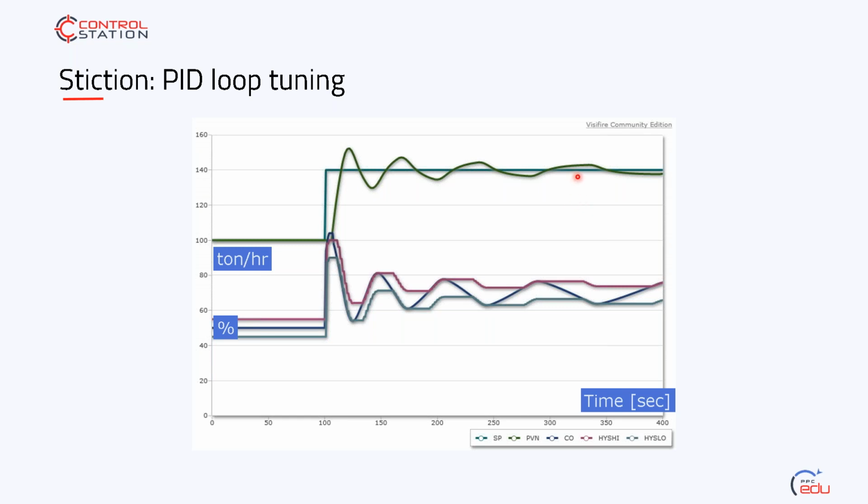You can set your own limits on that based on how close we get to an alarm with the loss of 1% of instrument range, and that should drive your decisions: are we going to do something about it now? Next week? Or on our next shutdown? You can track that through your predictive analytics. We have tools that will help you show that information, and you can then make decisions on when you're going to interact with that valve. You plan the shutdown, schedule it for between batches, between cycles, etc.